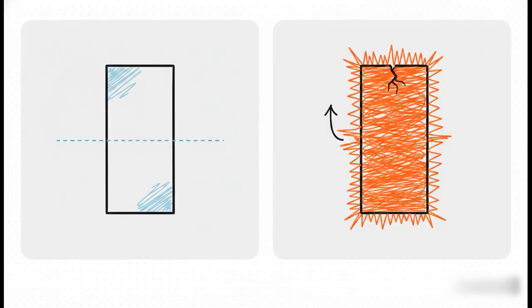To put it as simply as possible, when your distance from the neutral surface is zero, your strain is zero. When your distance is maxed out, way out at the very outer edge labeled C, your strain is at its absolute maximum. When you contrast that perfectly still, zero-stress neutral center with those highly stressed outer edges, intuitively, you can see exactly where a beam is going to snap first. It's going to happen right at those extreme top or bottom edges where the strain is maxed out.